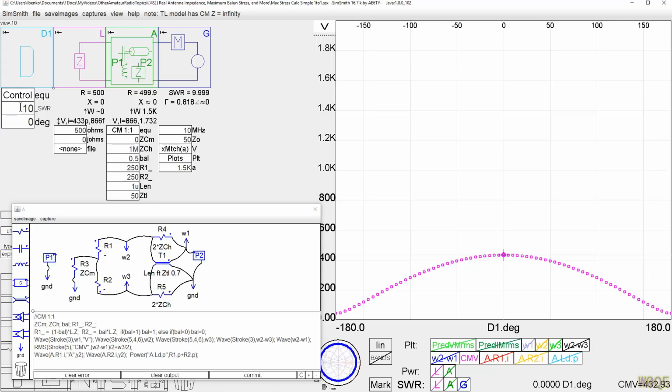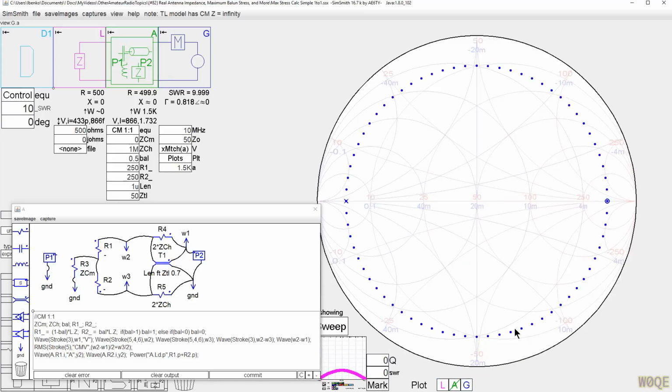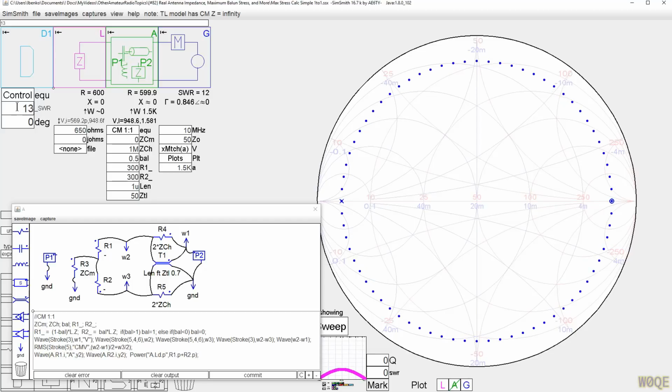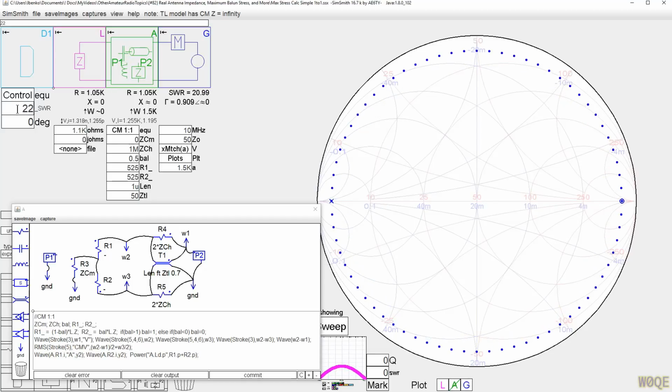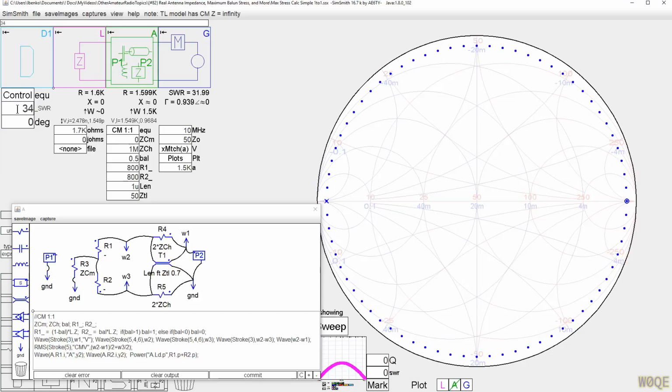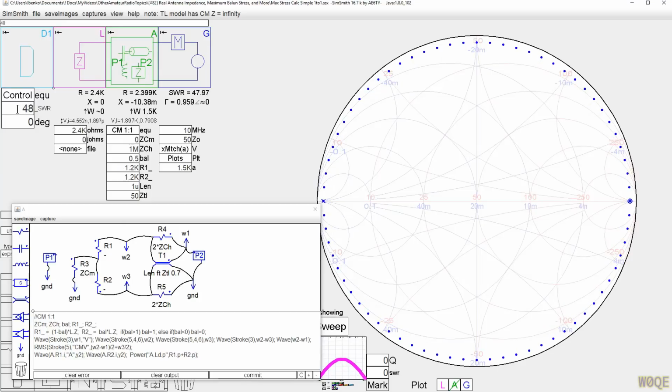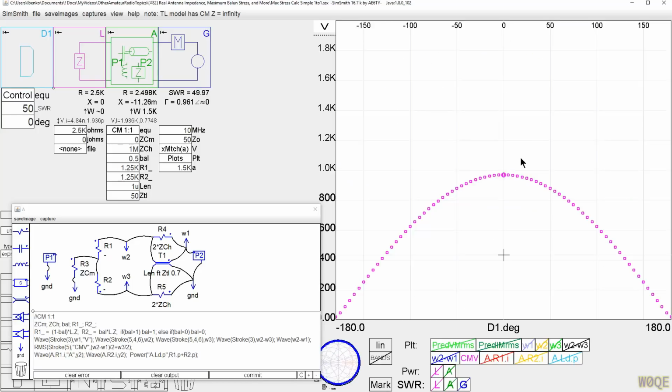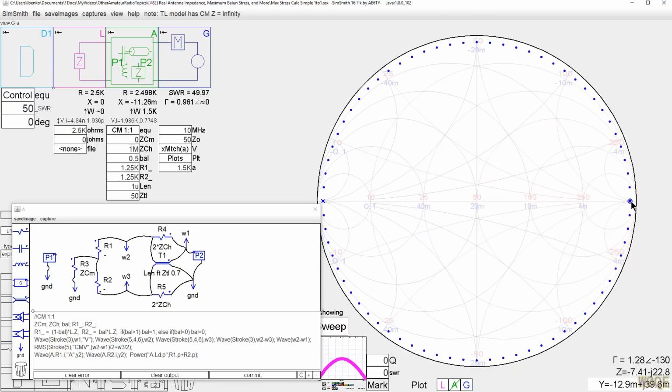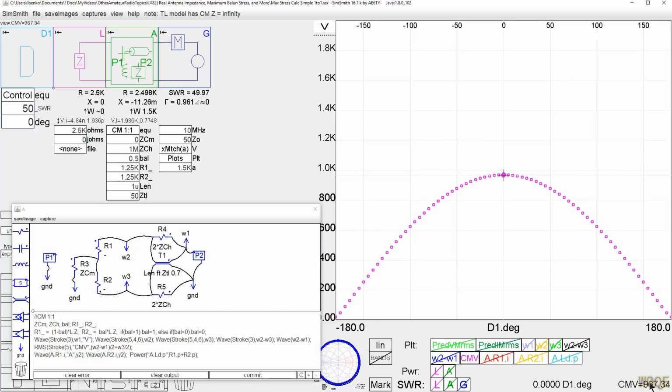Now, is a 10-to-1 SWR a good range of impedances to match to, or do I need to go higher than that? You actually need to go probably up to maybe 50 or 60-to-1 SWR, and I'll show you why in a minute. At a 50-to-1 SWR, the balun sees the most voltage at the zero degree phase point. The 0 degree phase point is right there: high impedance, high voltage. Over here, low impedance, high current. For right now, let's go back to this. We see this being 967 volts RMS at 1500 watts.